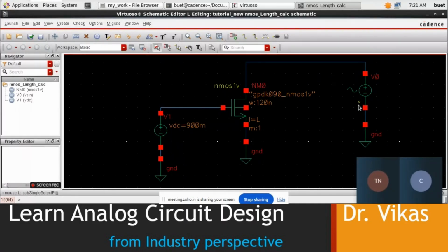So basically, you are putting in the AC supply here, which acts as an input. Now if you do V by I, whatever the value of R you get will be your output resistance, because you are attaching the source at the output. When you apply the source at the output side, it generates some voltage and there is a current. You divide them and you get the resistance, which is the output resistance. That resistance has to be very, very large, and you know how it is connected with your R.